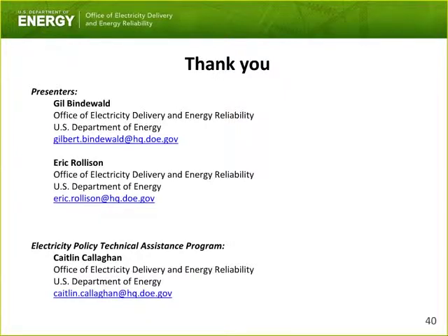And Gil, I would add on, and this is Eric, that there's also been a strong enforcement of vegetation management practices for the bulk system. Whereas I wouldn't say there were issues prior to that, there's very strong compliance to vegetation management practices now, which leads to better understanding of what Gil was talking about in some of his slides and some of mine, where the thermal parameters of how transmission lines actually react during high temperatures. We're in Washington, D.C. here, and it's a very warm day.